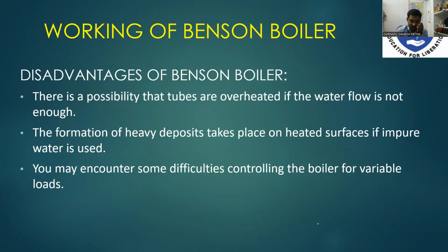And the disadvantages of the Benson boiler: there is a possibility that tubes are overheated if the water flow is not enough. The formation of heavy deposits takes place on heated surfaces if impure water is used. Some difficulties may be encountered in controlling the boiler for variable loads.